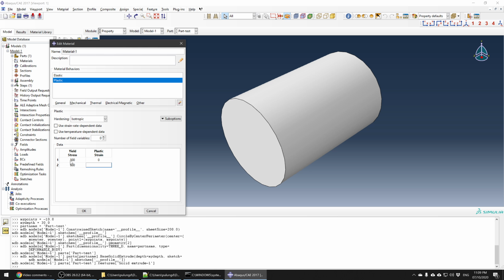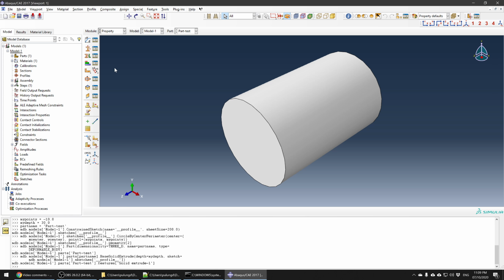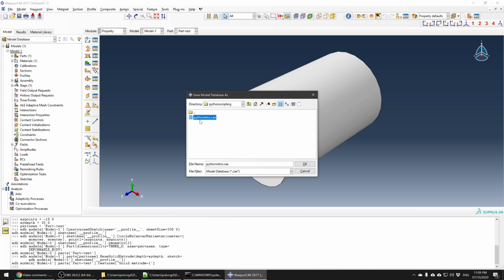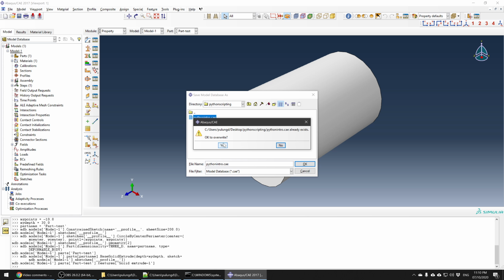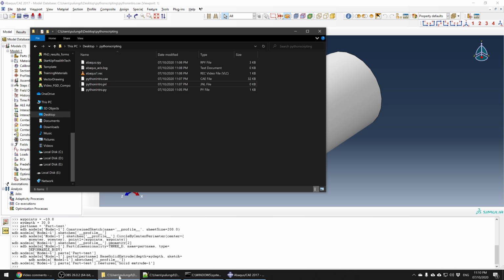Imagine now the model is a bilinear model. So basically you have elasticity and then you have a straight line. How do you call it? I forgot how to say it in English. It is not rigid plasticity. Rigid plasticity means no hardening. This one is linear hardening. Okay, you click OK, and then you save. You save to here. Okay, if you open it, the JNL file.